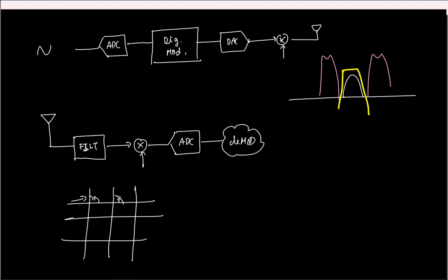So it is not just enough to say if the capacitance changes, you also need to know how much the capacitance has changed. And again, for sensing this, you have an ADC here. So if you have your touchscreen controller, it's again going to have a whole bunch of ADCs.